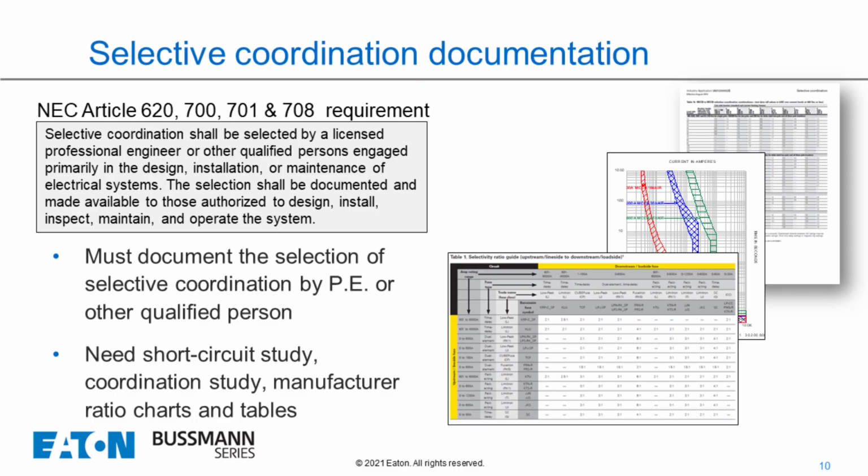All right, so on the right-hand side, we have your time current curve, which is in the middle. And we always use that. But then the charts on the bottom and on the top are basically charts that we need to look at to see if breakers coordinate and see if fuses coordinate correctly.